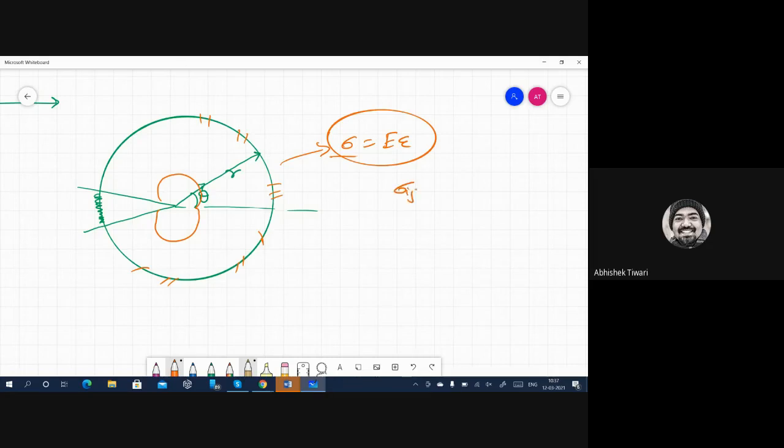What do I have to follow? I have to follow this, which also comes from elastic calculation. So I know theta is a variable and r is a variable. I know r for the boundary. I can just measure the radius of this scoop I've taken, and then I can systematically change theta with an interval of 5 degrees or 10 degrees, depending upon my ease and the amount of accuracy I need. What is k? Sorry, k is sigma root pi a.